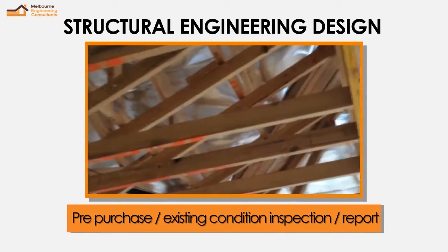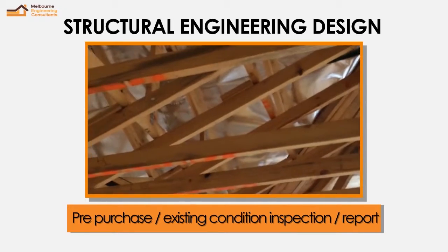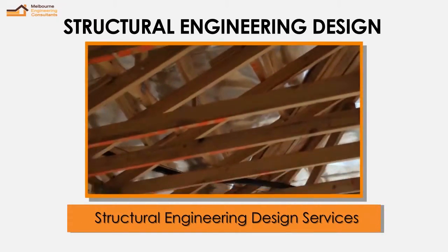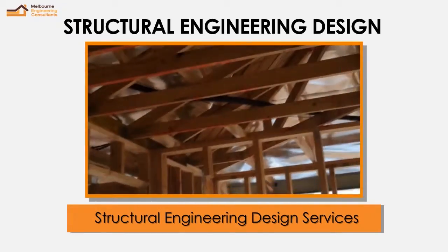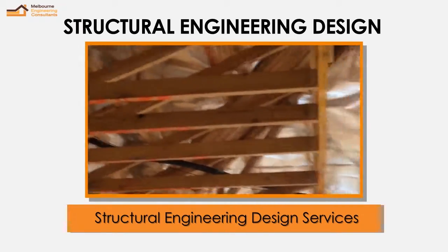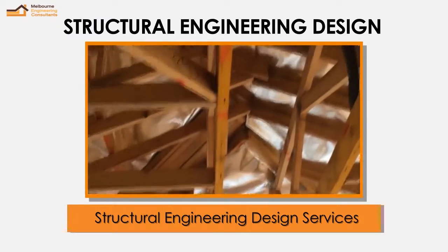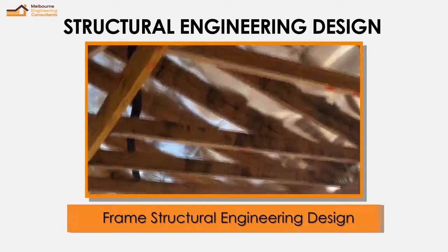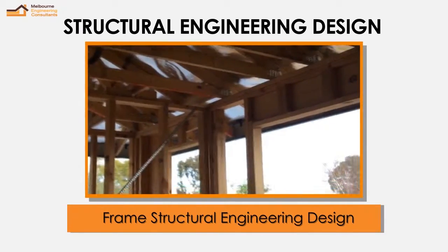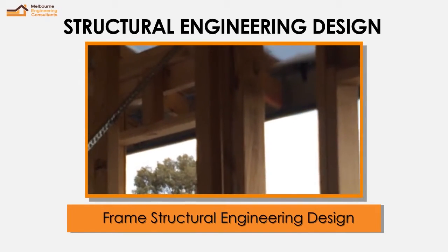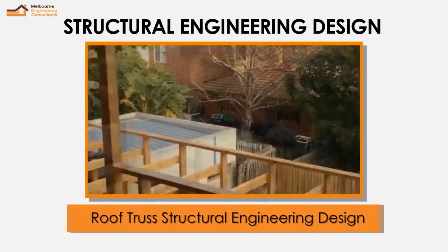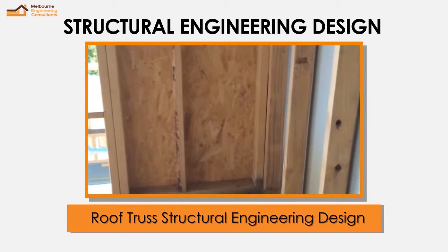G'day, it's Eugene here from Melbourne Engineering. Today we're out on site showing the same project, the construction stage. We're showing the structure. This one here shows the roof trusses manufactured by a third party and how they're connecting with my roof walls, and showing the bracing layout, showing the first floor lintels we have discussed in our structural design, and we are showing the bracing here, hardwood bracing on the other side, and this outside is the roof.